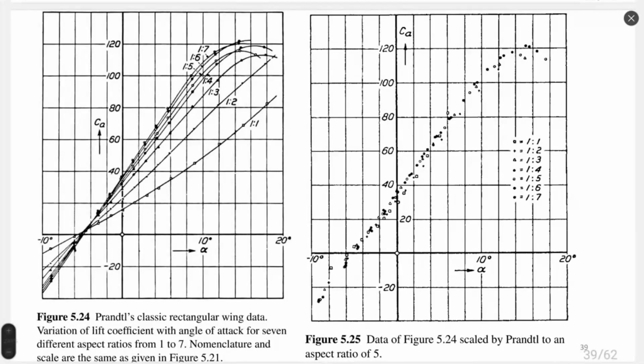Unfortunately, complex shape wings, especially aerodynamically twisted wing, when we change from one section to another profile of airfoil, or we change angle of attack from one section to another, which allows us to create extremely efficient wing, this theory cannot calculate. This theory calculates only simple structures, as usual, typical for any analytical model.